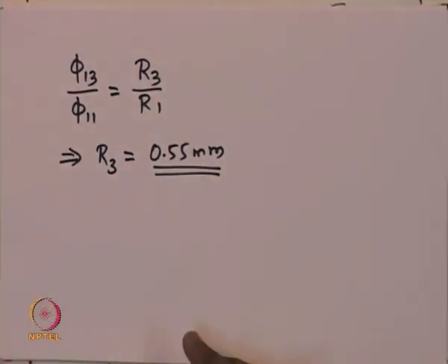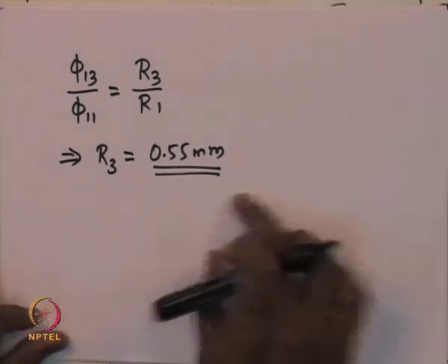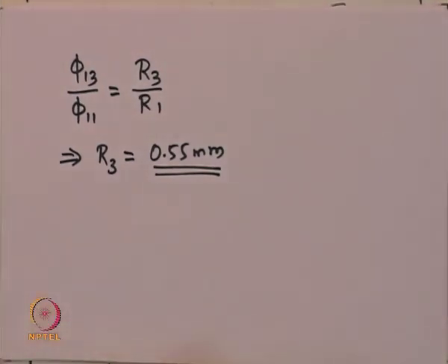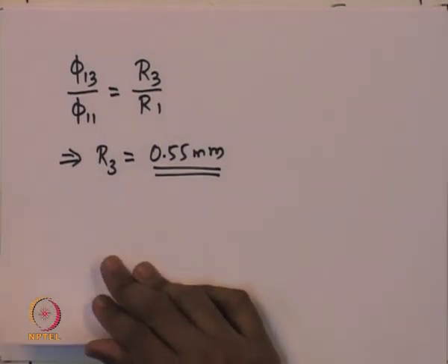The smallest pellet at which the internal diffusion will not limit the reaction is about 0.55 millimeters for the given set of experimental conditions. So, in this way, using some trial experiments, one can find out what the pellet size should be under which the reaction has to be conducted in order for the internal diffusion to not be present and not affect the reaction severely.